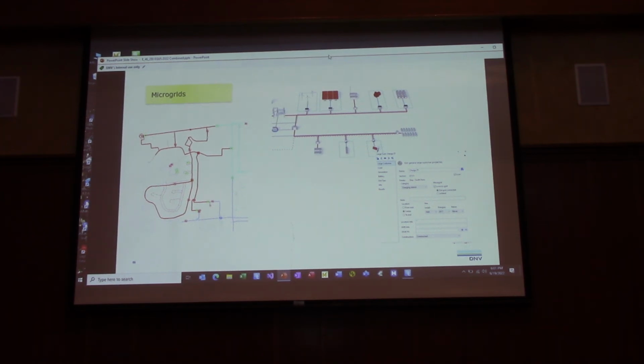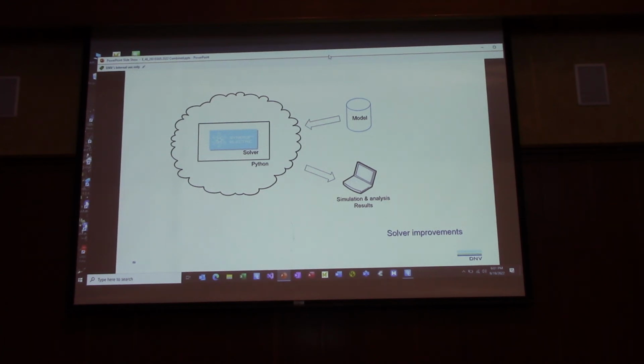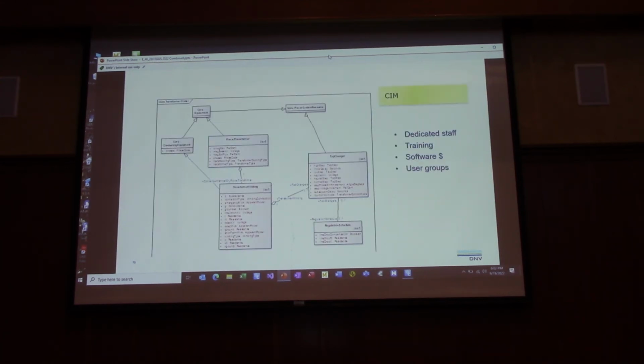And from what I understand, if you run microgrids, you have contracts for customers who have signed up to say, yep, you can curtail us. And so that information we need to have in Synergi so we know what customers to curtail. We know how to deal with the generation to try to balance the gen and the load in the model. So I don't think clients are at this point today, but soon. I think lots of us are going to be dealing with this. Chris Keever is going to talk about this a bit more. It came up this morning, so I'll just leave that.